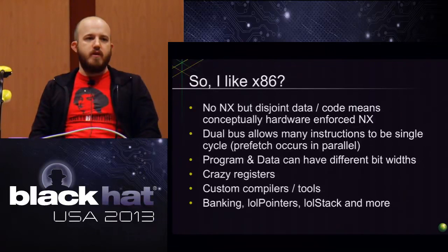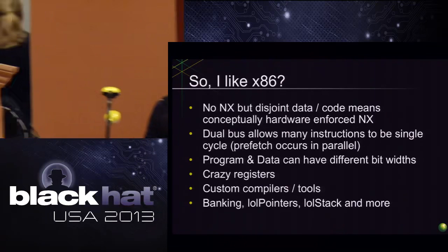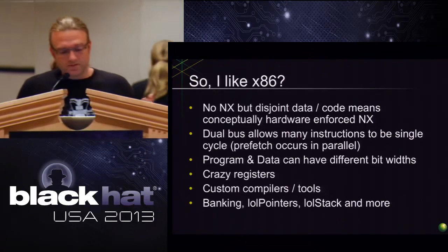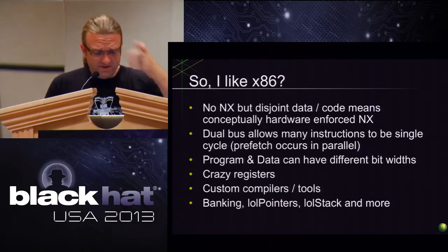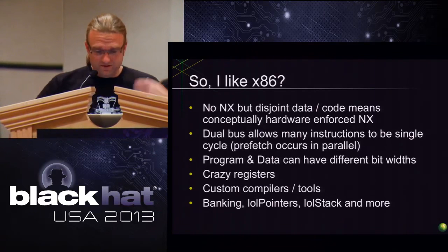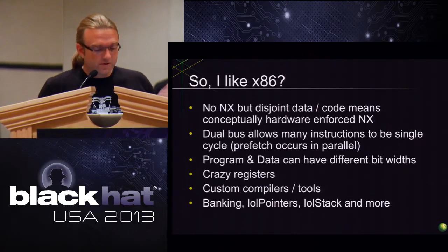So there's very few instructions that take more than one. Yeah. So what we started seeing when we start looking at Harvard a little more, the first headache we see is that because the buses are different, because it's physically separated, we can have program and data actually have different bit widths. It starts to be a pain, but not really for us.